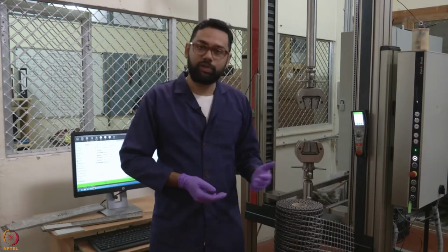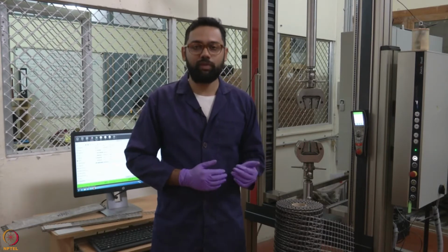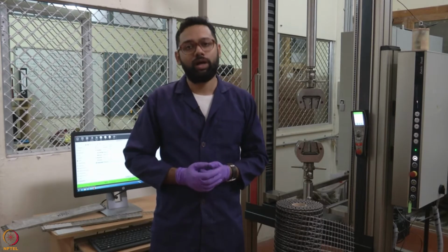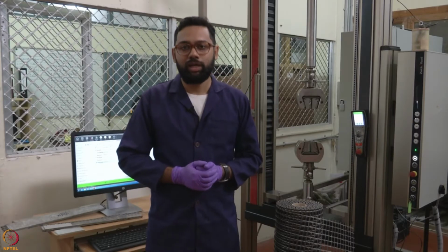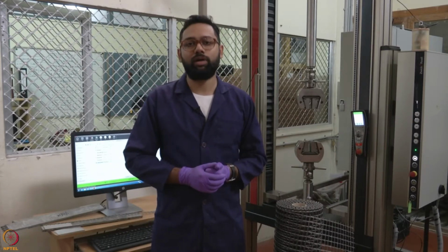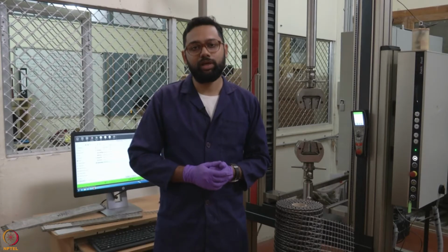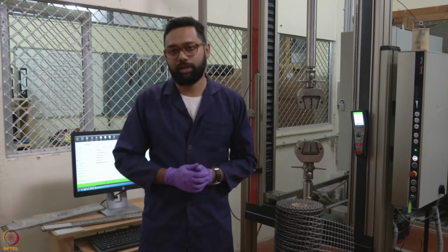I'll be explaining what a textile reinforced concrete is, how a uni-axial tensile test is done for textile reinforced concrete, and what factors we need to consider while doing a uni-axial tensile test. This test can also be done for other materials with fine grain aggregates, basically mortars or fine grain high strength concrete. There is a limitation for testing larger aggregate concrete, but this is basically as per RILEM test methods of 2016 for uni-axial test of textile reinforced concrete.